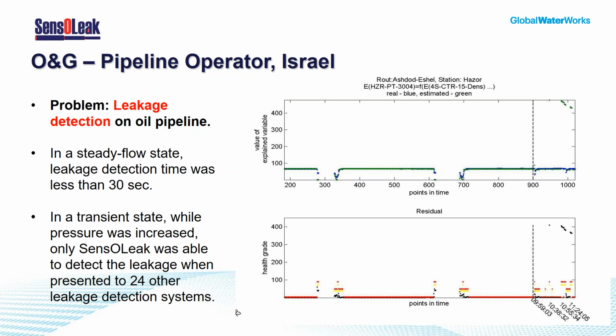And no one else could identify this leak, so-called, even hours before they opened the valve. We identified it within 30 seconds. Why 30 seconds? Because this is the interval the transmission rates were coming in. So as I said before, we are looking for correlation of pressure and flow.